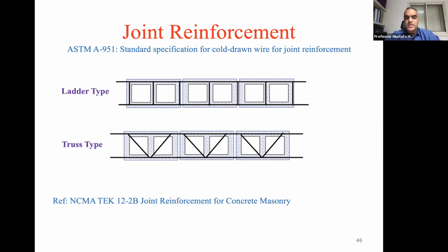Okay, we call this joint reinforcement, which is used to control, of course, cracking in the wall, and also it could be used as shear reinforcement. Okay, so if you have a shear force that's horizontal on the wall, in a masonry shear wall, and masonry walls are used a lot for that purpose as shear walls, this reinforcement can be used for that purpose.